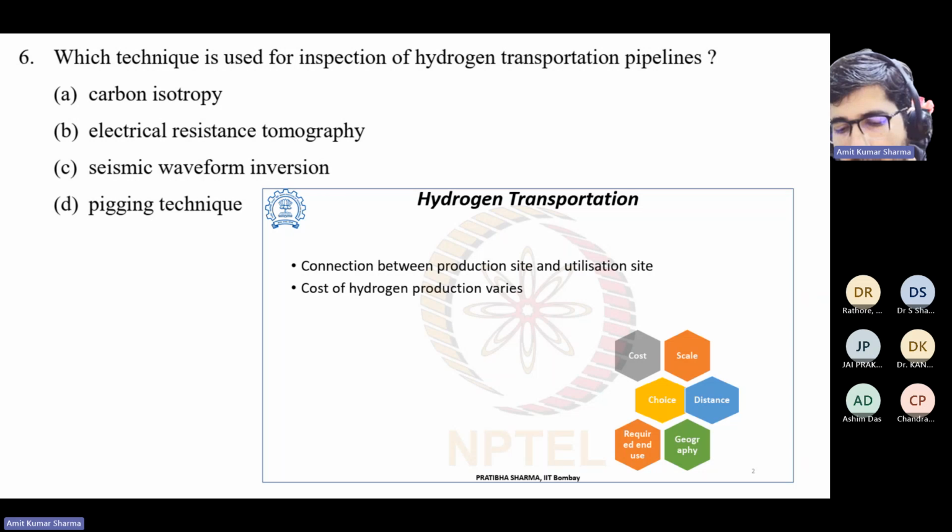As per the ISO standards, to maintain the pipeline and ensure smooth operation, we have a pigging schedule. It varies depending on the parameters, maybe yearly or every two years. So we do pigging for the maintenance of the pipeline too.